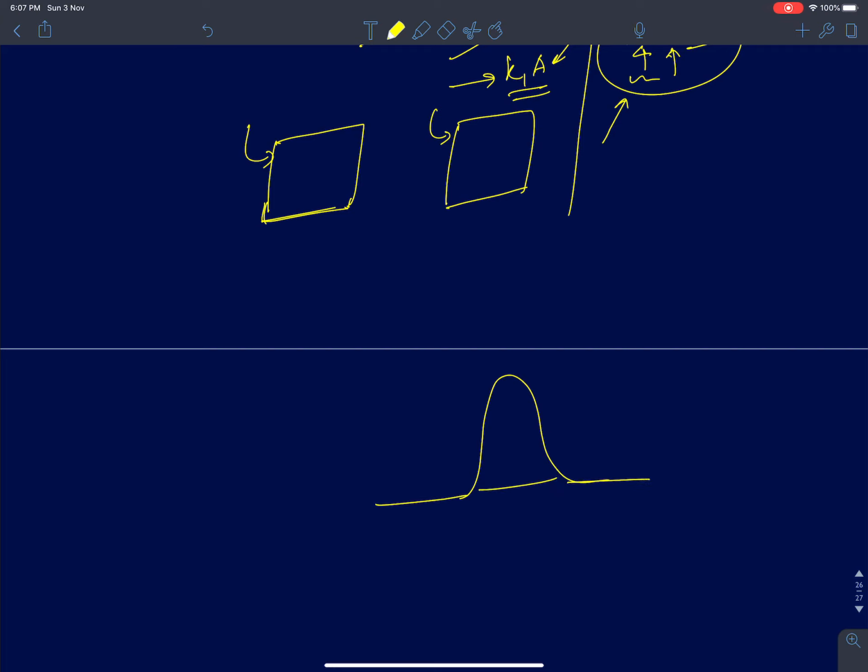When you apply two carrier signals very closely spaced within the band of interest, most of the harmonics will fall much outside the band of interest, so they don't matter to us. But the intermodulation components, or IM components, will fall very closely within the band of interest, within the RF band. That is why they matter a lot. Therefore we need a new metric which can tell me about the intermodulation terms.